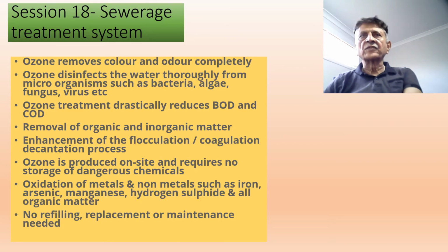The advantage of using ozone is as follows. First, it removes color and odor completely. So the water will be perfectly colorless and clear. Ozone will disinfect the water thoroughly from microorganisms such as bacteria, algae, fungus, virus, etc.